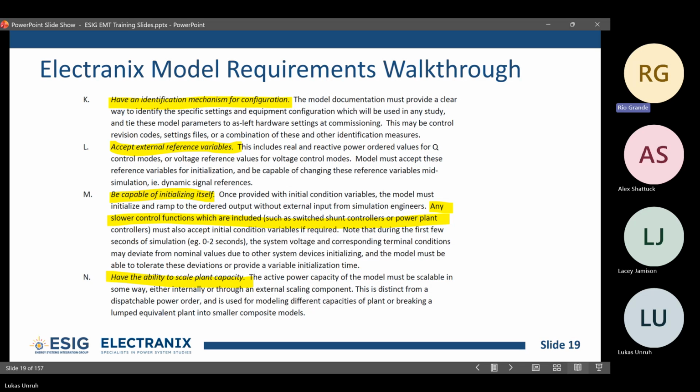But I saw some other recommendation. They just modeled one IGBT level, maybe around 2 kVA, then used the interface transformer in PSCAD and scaled up the voltage and current on the other side. Is there any limitation on the second representation, you think?